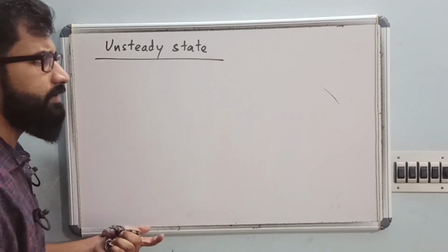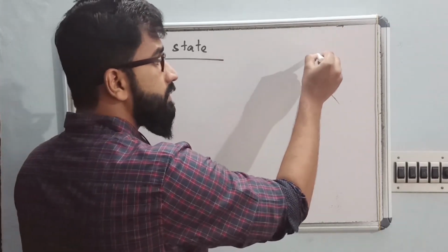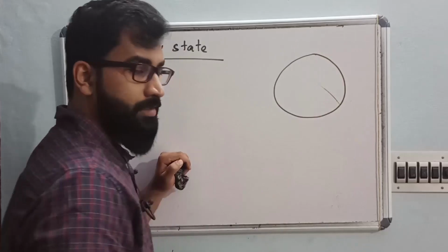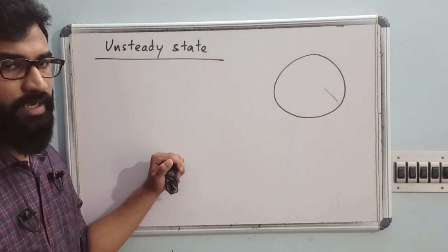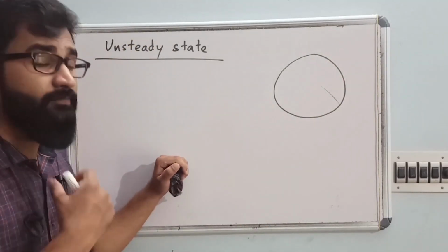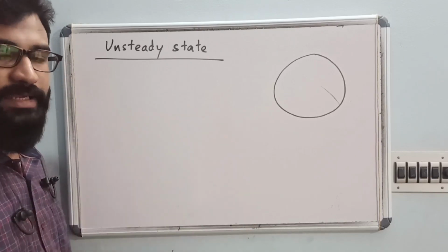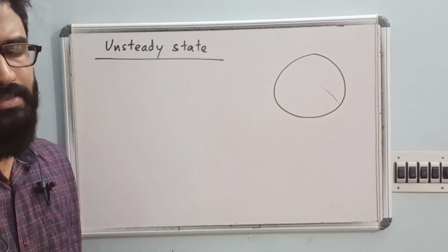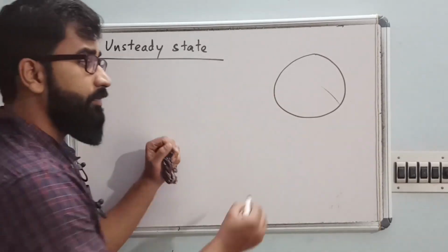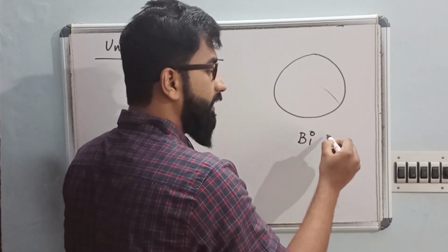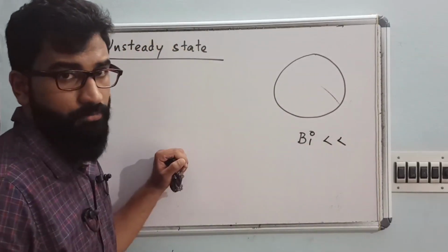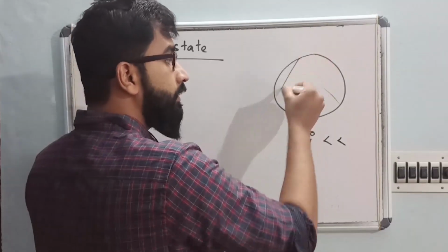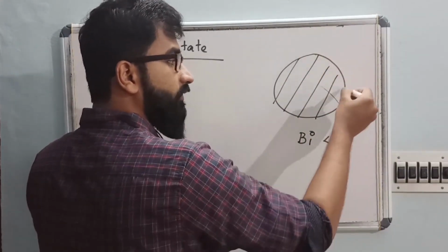It's very simple, right? In this unsteady state heat transfer, we have the lump heat capacity analysis. Maximum questions so far from GATE are from only lump heat. When you are revising, first go through lump heat, then go for the other cases. Lump heat capacity analysis is valid when we have a very low value of Biot number. That is, our assumption is that the complete temperature of the body is constant.